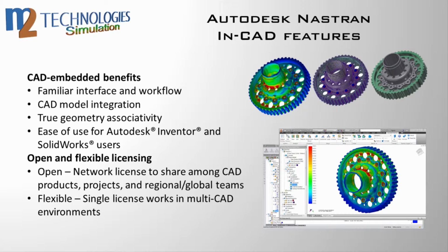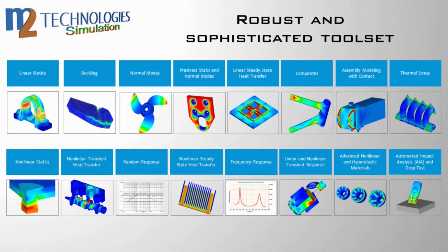This eliminates the need for a standalone simulation software package. Autodesk Nastran InCAD supports a wide array of analysis types. Linear static stress and normal modes are commonly found in embedded simulation systems. Nastran InCAD takes it to the next level with advanced nonlinear, static and transient stress, dynamic response, and thermal analysis types. Let's look at some quick examples.